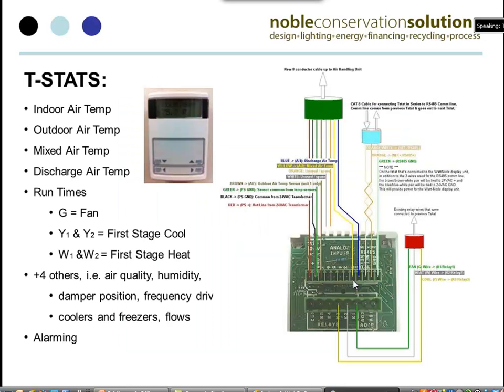We use thermostats, programmable controllers as thermostats, that help us collect this information, obviously taking what's read off the sensors connected to these thermostats, both indoor and outdoor air temperature and a number of other things, and feeding that into the InduSoft system so they can see it in real time, as well as in the database for certain analysis and different types of trending.